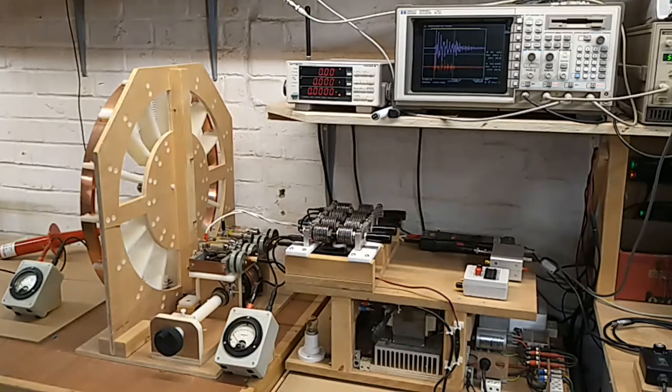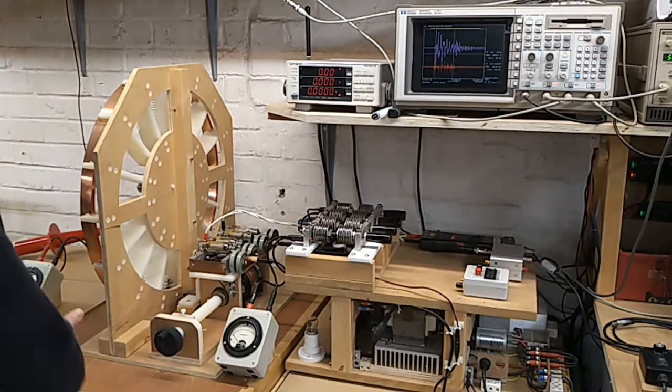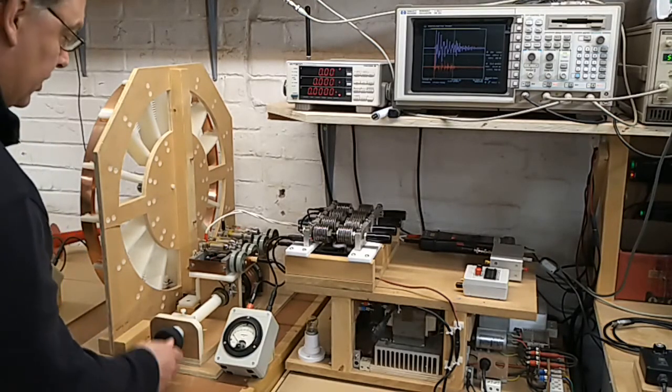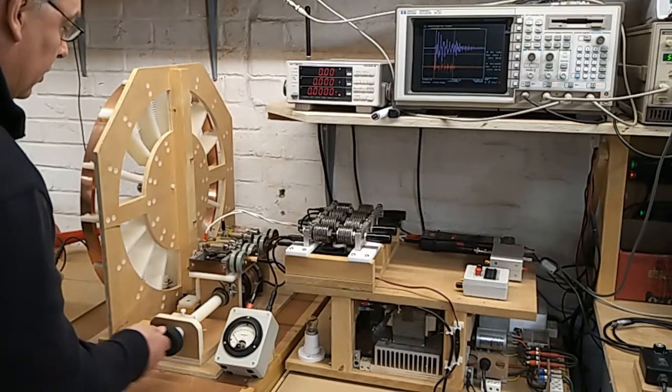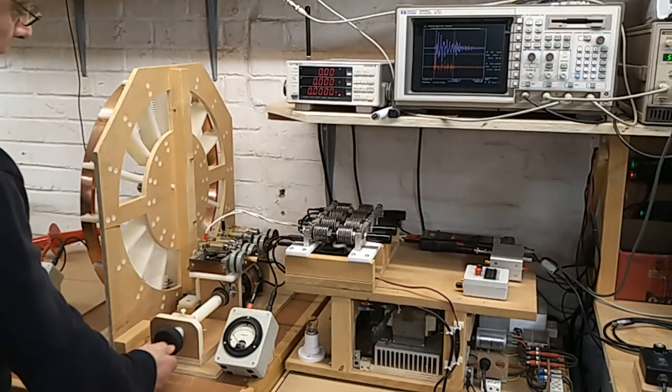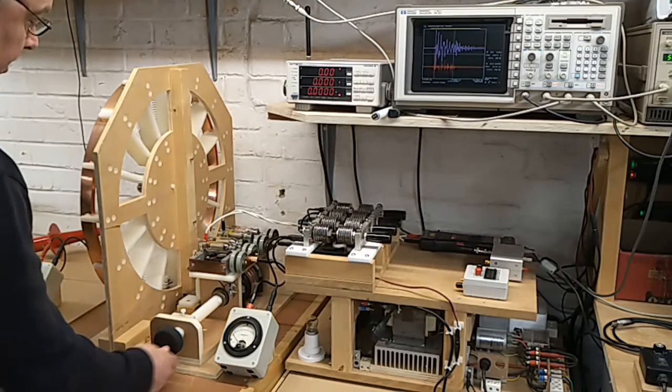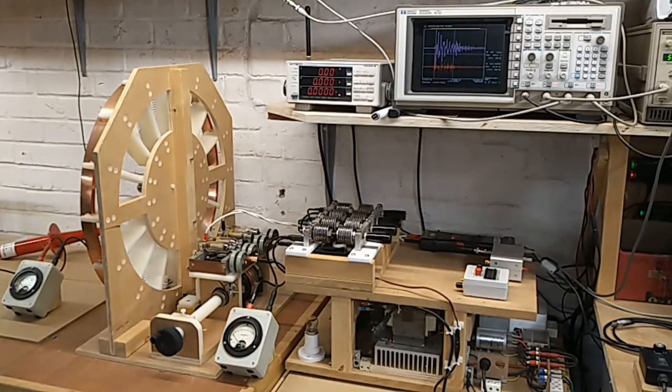This works exactly in the same way as the previous part we did in the transference of electric power. And we can wind that all the way closed, and we can wind that fully open all the way up to, that's about 20 picofarads fully open, and when we close it, it's around about 1200 picofarads fully closed, and that's in parallel with the two-turn copper primary strap. So what we're going to look at next is the effect of tuning this and find out what kind of impact that has on the circuit.